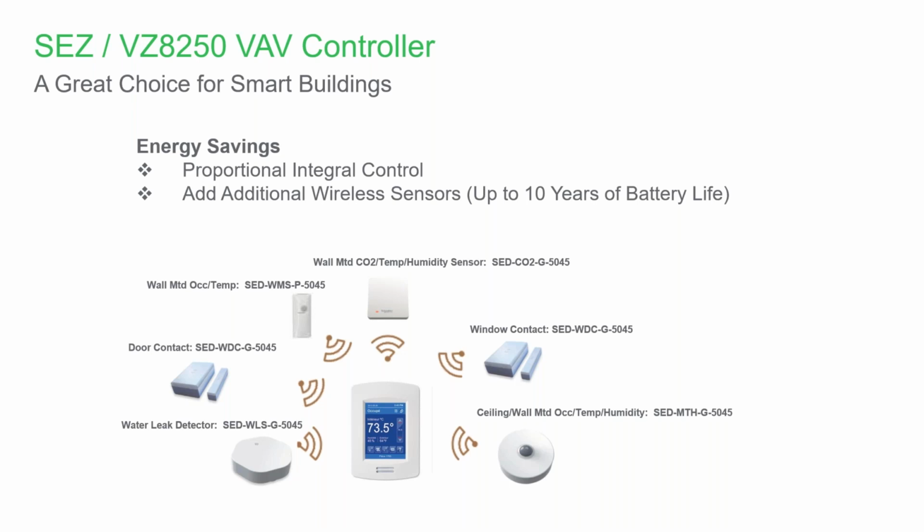And what we see is, imagine a VAV box that has a temperature sensor in one room and it feeds 6 rooms. Typically, room number 1 is the one that controls the temperature and any kind of set point and the comfort zone, the comfort of the other 5 rooms.